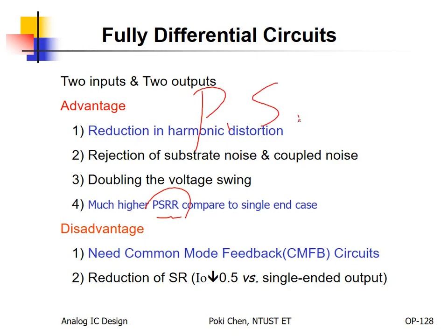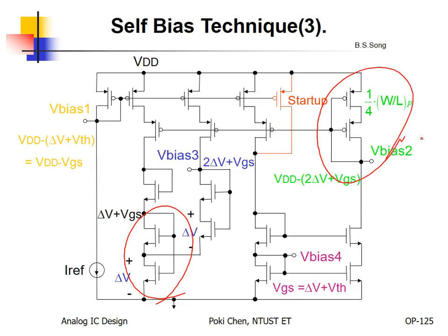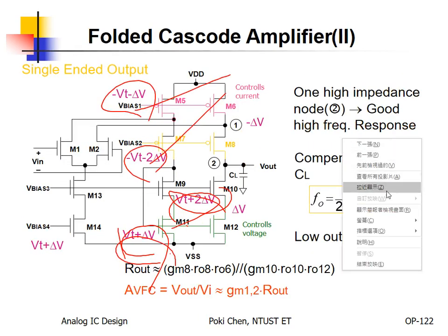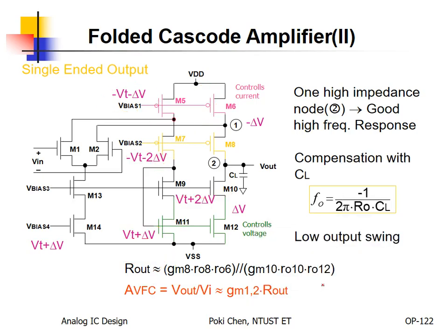power supply rejection ratio. Why? Because if you go back to see the overall circuit, for example, for some reason, the VDD is increased. Guess what? How about the Vout? Usually, it is also increased, pushed upward.